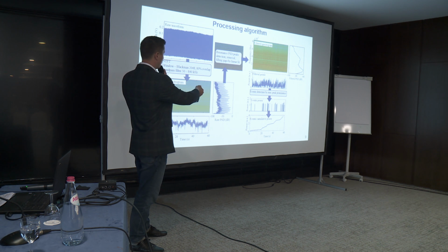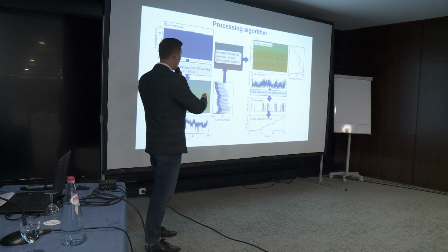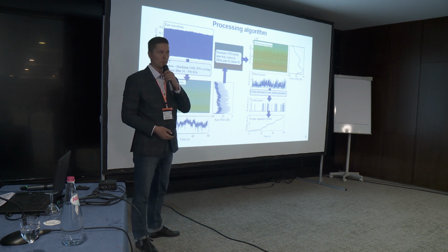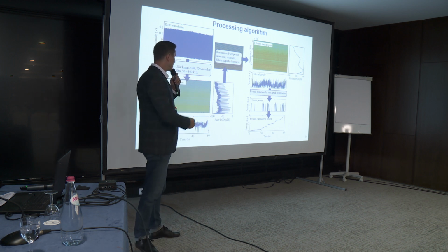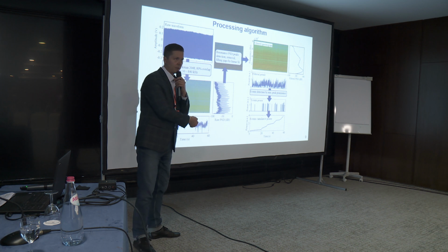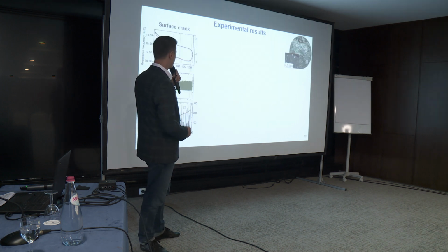Then, if you take this filtered spectrogram, where this is the time axis, and sum up all the power at every time moment, you get the filtered power. Then you can apply a simple threshold method, and you obtain the events power, and if you sum that up, you obtain the cumulative power of acoustic emission events.